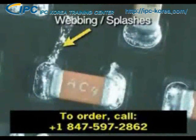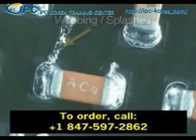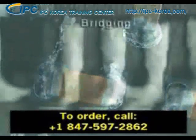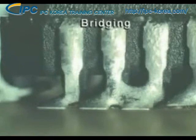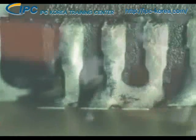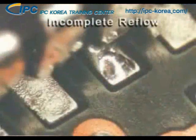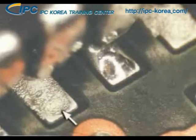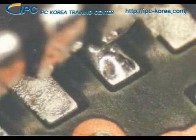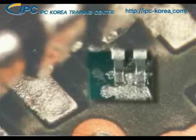Solder webbing is a defect that occurs when a film or splash of solder covers any area of the assembly that should be free of solder. Solder bridging is a connection of solder across conductors that should not be electrically joined together. Bridging is always a defect since it misdirects the electronic signal. Incomplete reflow occurs when insufficient heat is applied to the assembly during the soldering operation. This means the solder paste may not have properly wetted the surfaces to be soldered and will not form an acceptable electrical and mechanical connection.